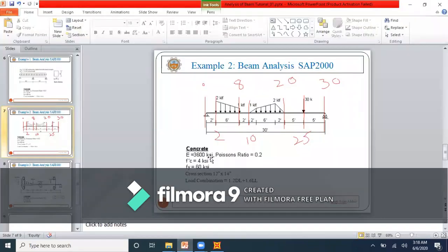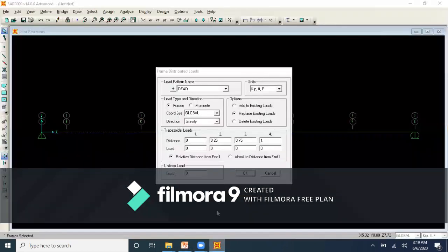So in this example, this particular load can be applied by entering load at 2 locations, at this location and at this location, right? I will consider this location 0, then it is the other location, right? So how will you apply this load? So at distance 0, and what is this distance 0? This distance 0 is represented by this point, which is point B. This is the location of this 0 distance. At this 0 location, the load is how much? It is 2 kip per foot.